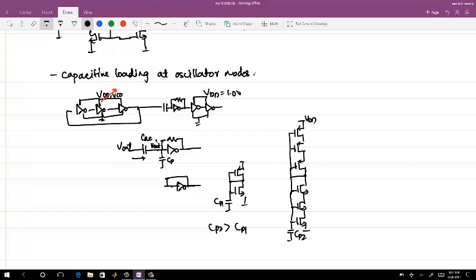One is the power consumption in this bias itself in comparison to two, and the other is the capacitive loading on the oscillator. So actually, the total power increases. And this is loading at only one node of the oscillator. If you are loading only one node of the oscillator, then you are causing an asymmetry in the phases. All the phases will not be equally apart. So you need to check for that too.